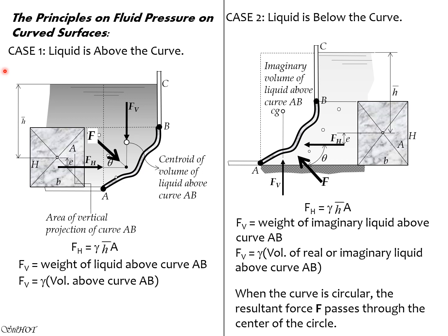So that's all for this lesson 3, the principles. I hope you will not forget the formulas, and other important formulas would be, you should recall the moment of inertia so that you can locate the center of pressure. Remember that the force is acting at the center of pressure, not at the centroid of the area. So remember that.